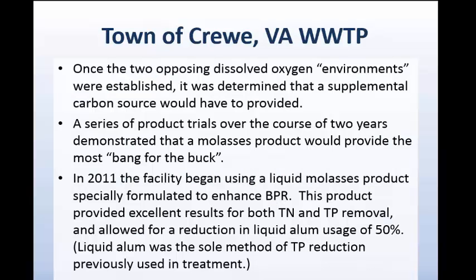Once we had those two opposing dissolved oxygen environments established and in place, we found through some testing that we lacked a supplemental carbon source. For simplification, carbon source is equivalent to food. And even further simplified, the philosophy is if we keep them eating, then they will continue normal metabolism, which in the anoxic zone, the zone we are trying to remove the nitrates from, the NO3, if they're eating, they're going to continue to convert nitrates to ultimately nitrogen gas.